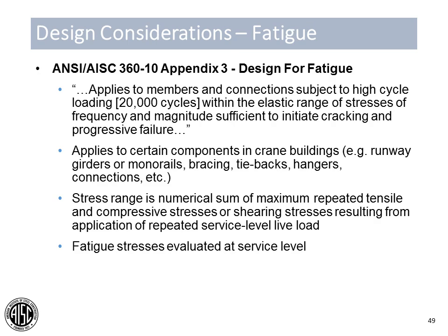And then fatigue. This is the big consideration that most people don't consider since it's so different from typical structural analysis. The AISC specification includes in Appendix 3 the design requirements for fatigue. Fatigue design applies to members subject to high cycle loading within an elastic range of stresses of frequency and magnitude sufficient to initiate cracking and progressive failure. Now there are two specific items there that we need to look at: the elastic range of stresses, so the magnitude of that stress range, as well as the frequency of that stress range, and we'll define that shortly.